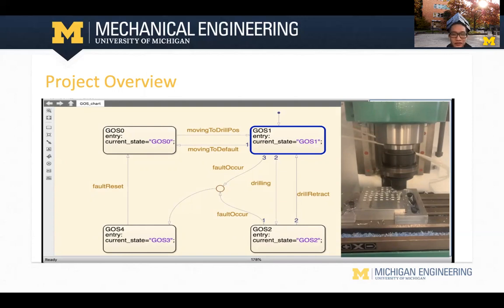The system in this video is actually done using a threshold-based method, which is really sensitive to changing conditions. That's why it's so quick to respond, but this is not ideal for practical application because it's sensitive to operating conditions and it doesn't scale well. So what the system should do is to tell us how the machine is interacting with the workpiece in real time for a given time instance.